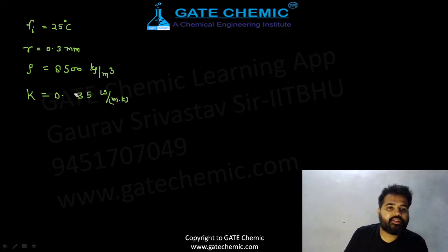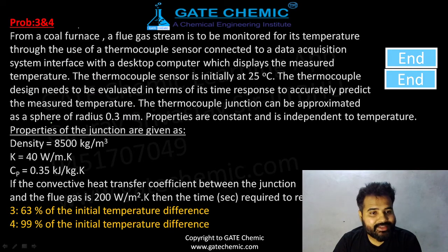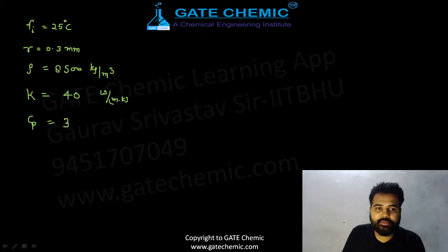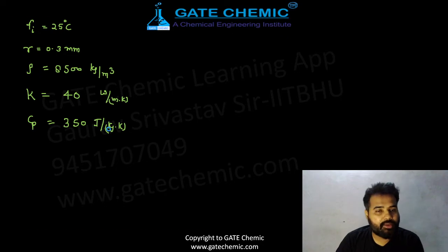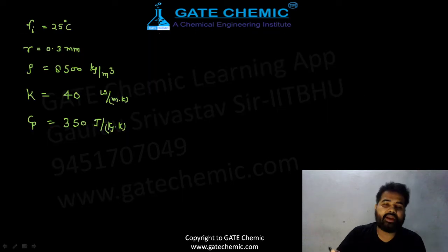K is 40. Next data, Cp. Cp is also given in our problem. Cp is 0.35 kilojoule, so beta, first you have to convert this into joule. In joule, it becomes 350 joule per kg per Kelvin. Okay, completed. Beautiful. And the convective heat transfer coefficient between the junction and the flue gas is 200.